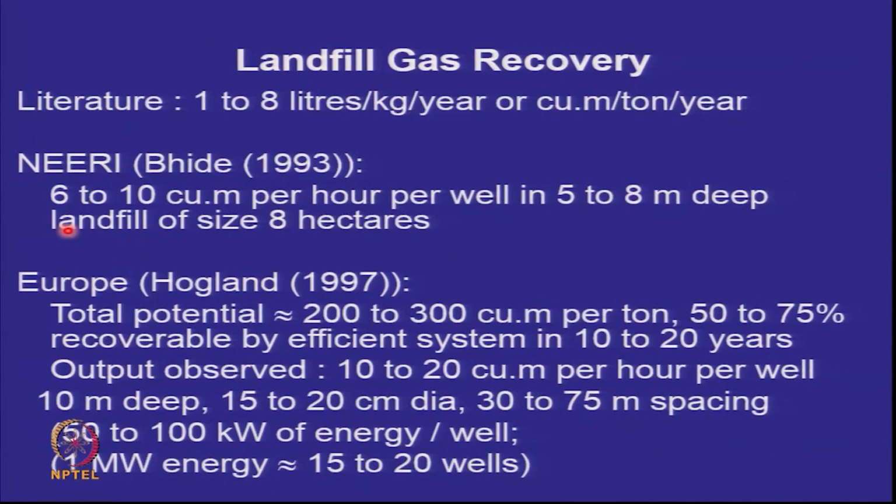And if you look at the gas production rates reported from wells, if you have a waste mass and you put a well in it, then you get 6 to 10 cubic meters per hour per well. This is India, in 1 or 2 landfills. And if I look at Europe, here it is 10 to 20 cubic meters per hour per well.